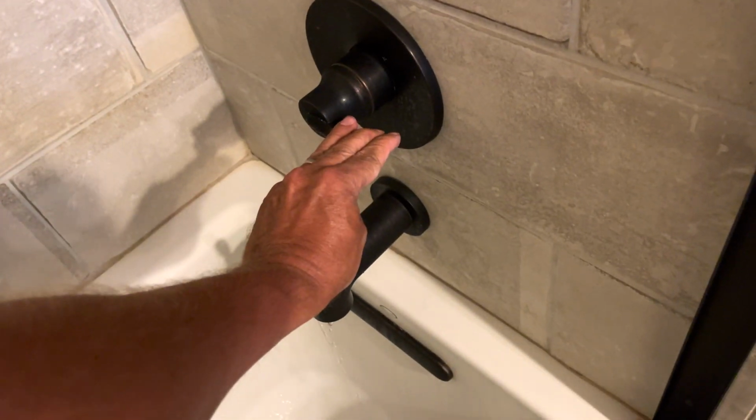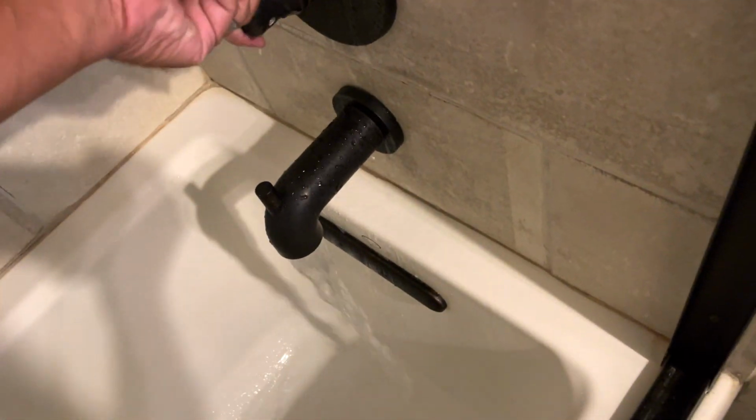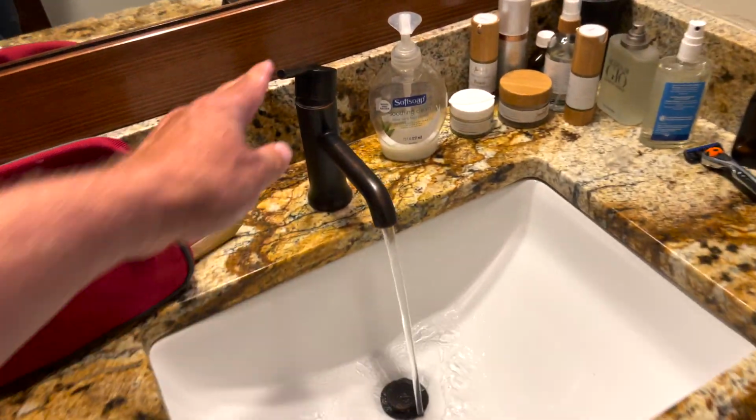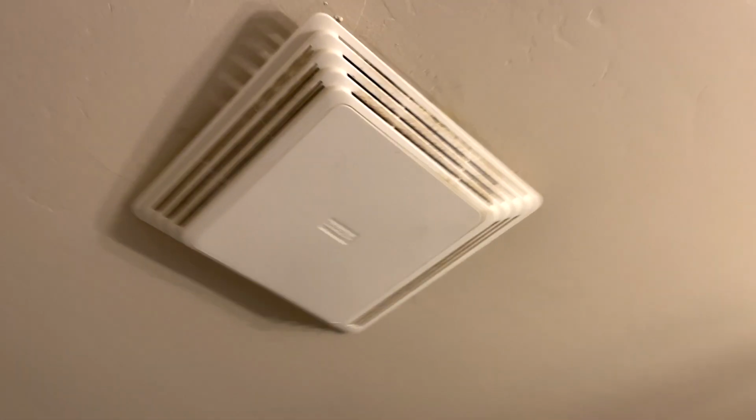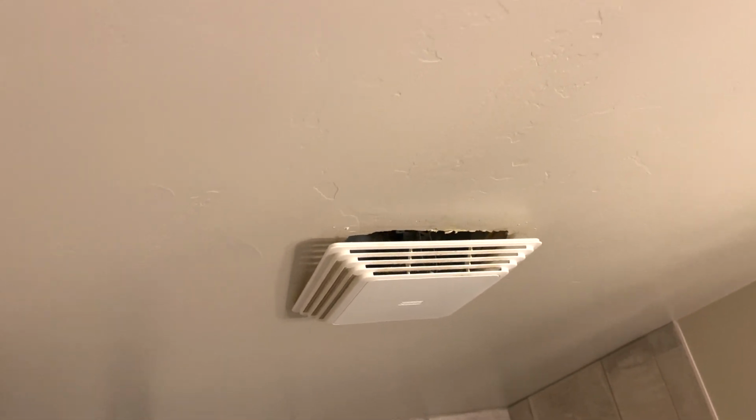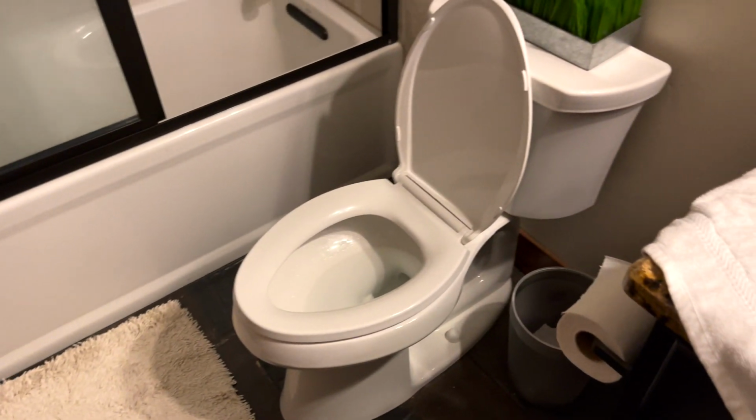There's a register. Pull that up. Nothing unusual. The door closes. Look for water leaks at the corner where the tub meets the floor. The tub surround, the tiles, the sealant. That all looks good. The grout. No defects observed. Functional flow, hot and cold water. Turn the water off. The window does not open, so we have an exhaust fan, and there's that loose hood at the master bathroom exhaust fan. And it all looks good.